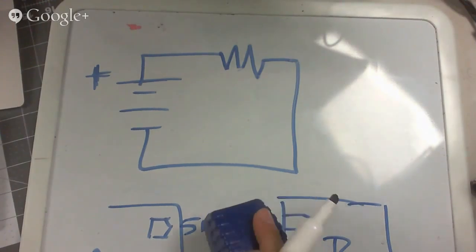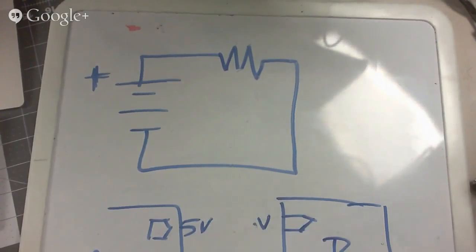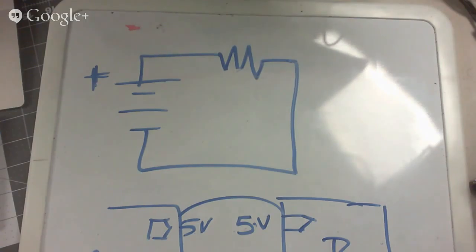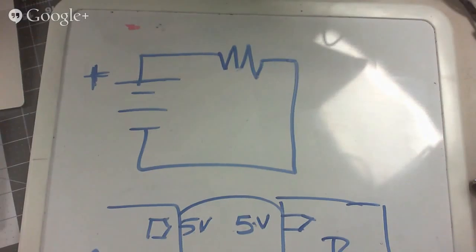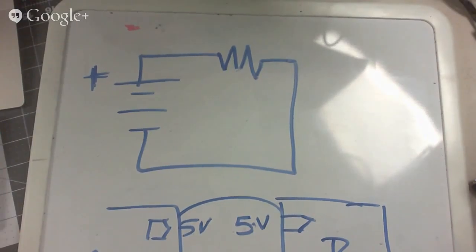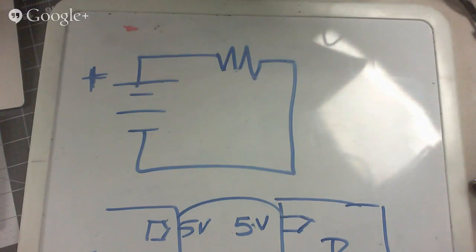So let's assume both devices are 5 volts. We can go ahead and connect a wire. Boom, we're fine. Now, let's say this guy says, based on my circuitry, this is a black box, I will draw 100 milliamps. So long as device A can source 100 milliamps, you're cool. If it can source more than that, if it can source 500 milliamps, that's fine.